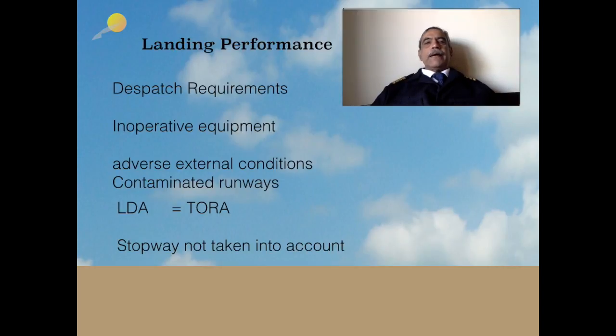This lesson is about landing performance, not very demanding, nevertheless an interesting lesson. The dispatcher, before dispatching the aircraft, has to ensure that the landing performance meets the landing distances required as stipulated in the legal books. Generally, the landing performance may not be very limiting, and if it were to meet other takeoff and en route requirements, then it will obviously meet landing requirements.